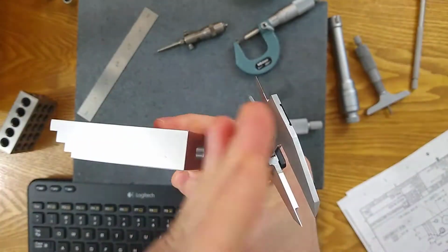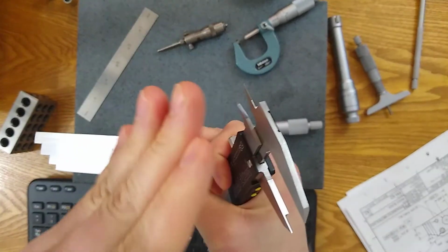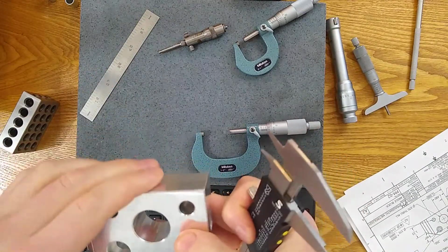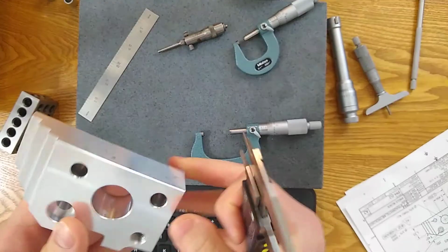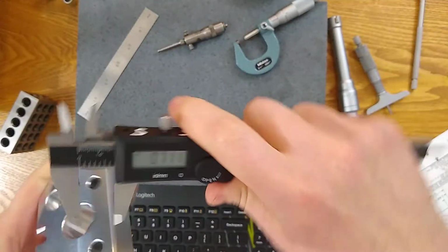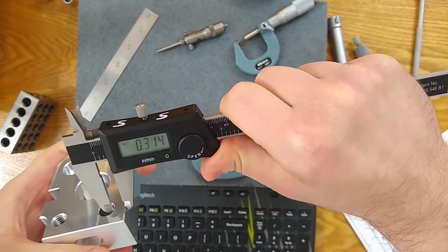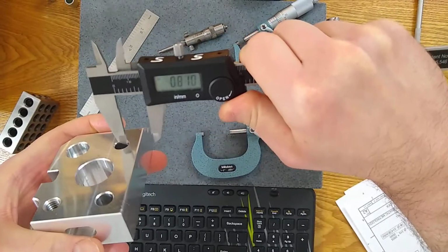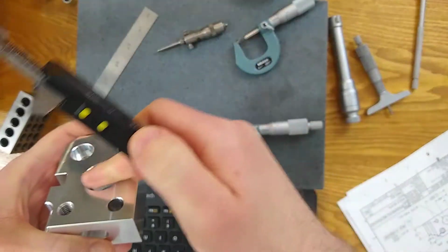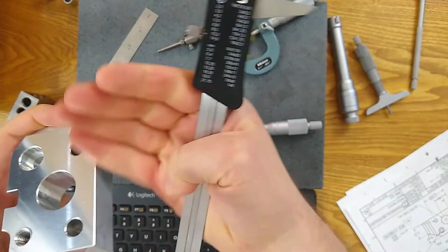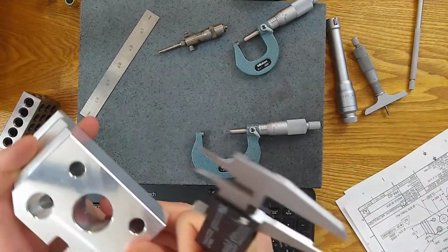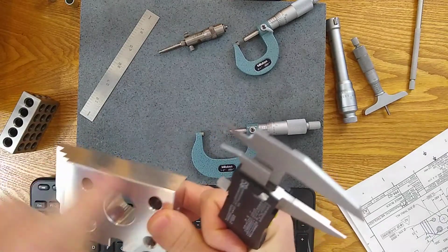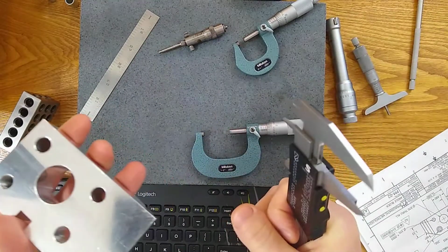It could be very bowed due to the manufacturing process. It could be unfinished. It could be rough because of chatter. So sometimes, if I did all 3 of these holes, they're all different sizes, so I'm going to get different numbers with my caliper. That's not surprising. But when you do the math to find the center point, you might find that there's a bow one way or the other. I might see that the chatter is really affecting each time I measure it. So some holes are in and some holes are out, and it's hard to repeat.